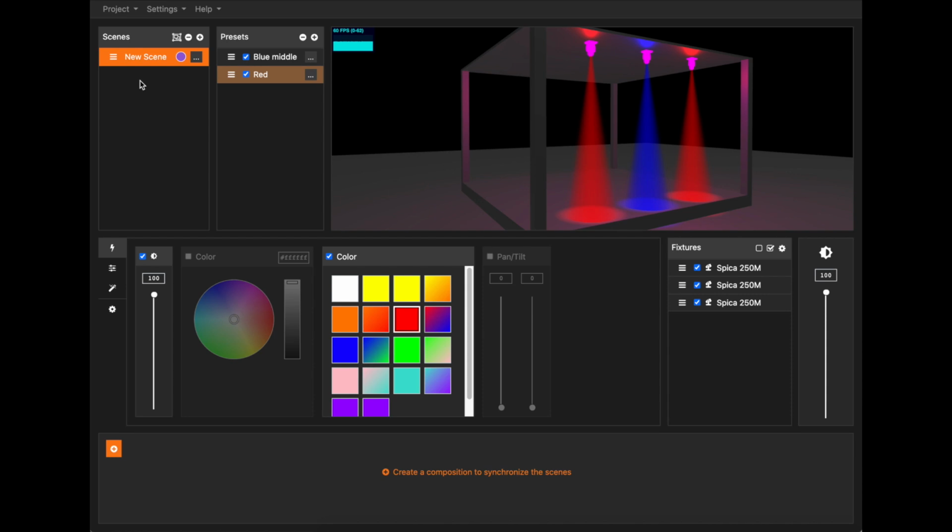And by the way, if you're working on a Rocket Show device, you can enable live preview in the lighting settings of Rocket Show, and then everything you see in the preview here in the designer will also go directly over a DMX device, if you've connected one, out to your fixtures, and you will see in reality how your changes here affect your fixtures.